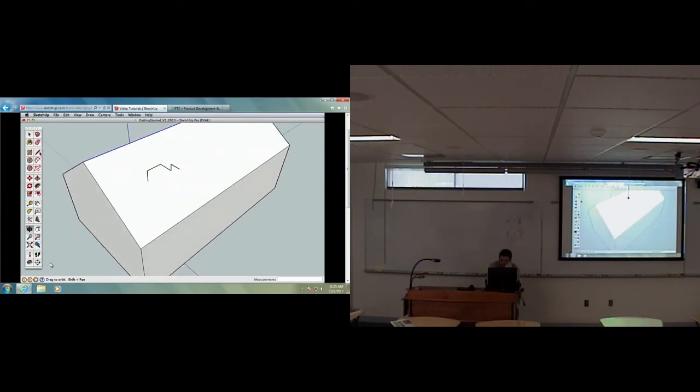To draw a chimney, we could approach it in many ways, but we'll use this method. We'll draw the side profile shape, then use the push-pull to create the full chimney. Drawing with the axis directions will help us create the correct profile in 3D space. Use the Eraser tool and click on any edges you drew to erase them.